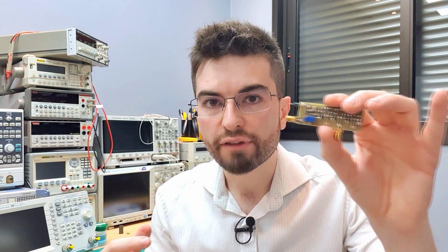So why do we have this prototype, this little PCB here? I'm working on a project where I need a noise source, and I'm going to talk about this because I think it's very important for you to understand my line of thought to arrive at this board. This is my first attempt at noise generation, so I didn't have any background, any practical understanding about how noise sources and reverse-biased base-emitter junctions behaved. So I made this little board as an experiment, to come here to the bench and grab this practical understanding about the behavior.